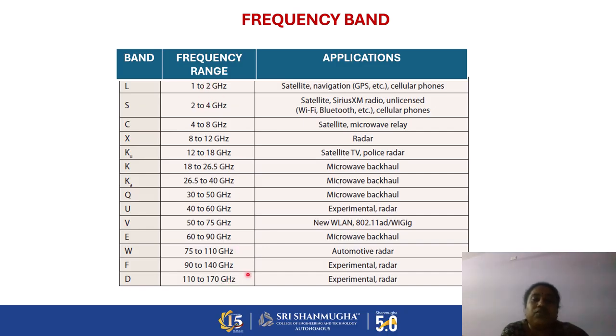Based on the frequency range, the wavelength, and the applications, we can design the FSS unit cell according to the frequency band and applications. So before designing the FSS structure, we need to first select the frequency range and then the applications. Based on that, we need to design the structure. Based on the structure, in the previous slide I discussed the classification of the FSS. So we can utilize single layer, multi-layer, and stacked layer structures.